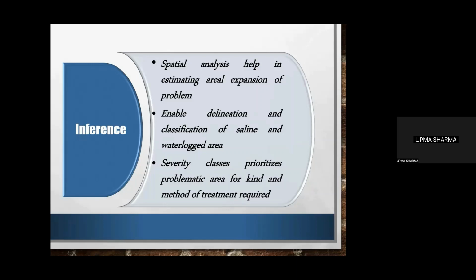If it is a potentially waterlogged area and it's not required, you don't have to install the SSDs, as it is quite costly, and you can treat the area with on-farm development. Also, you can protect it by lining the canals or the field channels, or other treatments. Some water management practices, proper water distribution systems, can be used for a proper distribution of water into each and every field, so that the area does not get waterlogged so easily, especially at the tail portion.